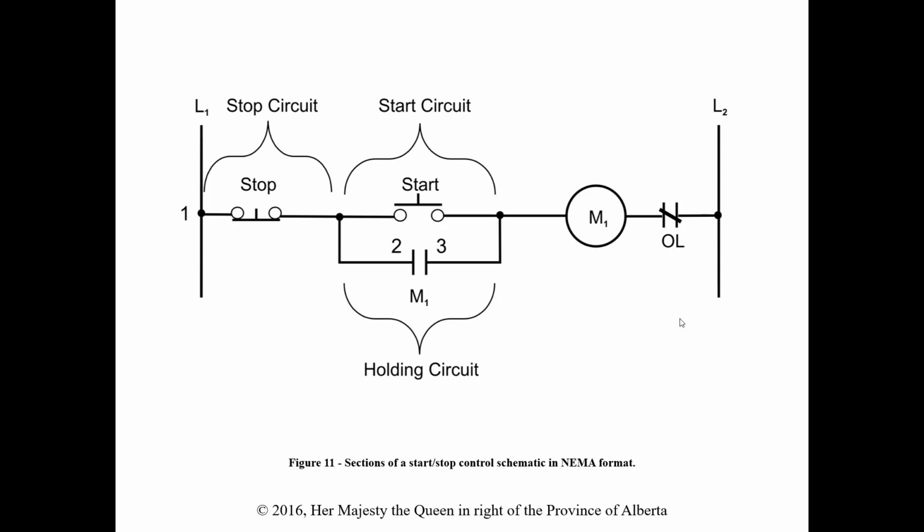Again, we talk about the two different types, whether it's low voltage protection or low voltage release. Once we get into the start-stop scenario with a hold circuit, with these momentary buttons, we're definitely into a low voltage protection scenario, so that when the circuit comes back on, we would have to physically press start here.